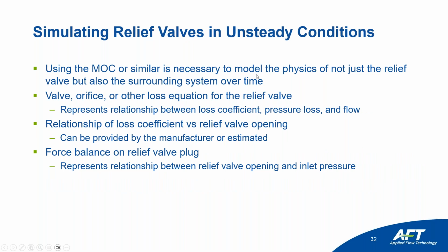Similar to check valves, the way that we recommend to do that is to perform a system level analysis. We recommend running simulations. Obviously, AFT Impulse using method of characteristics is one such simulation for that. But it's very important to characterize the balance between your system as well as your relief valve itself. So there needs to be some kind of way to talk between them. AFT Impulse does have that, and there's a number of different ways to do that, which we go over in the paper. AFT Impulse really follows these two mid bullet points here.